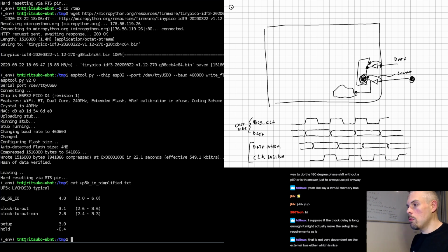No, that's really nice. Is that the additional delay of the clock input turns out to meet the requirement of the FPGA, independent of the bus frequency? I mean, as long as you don't go too fast to not actually meet the setup time at all. But definitely very nice that it just happened to work. Yeah.